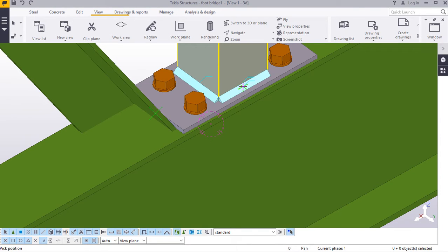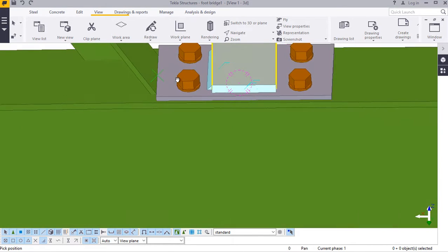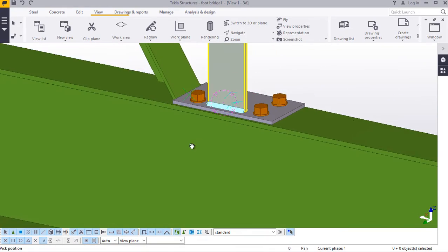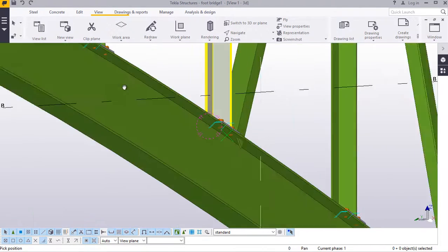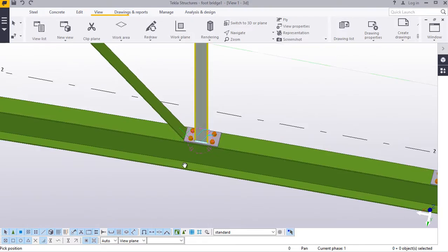I want to rotate the model about this spot. The moment you pick the point you want to rotate the model about, you see the cursor change to a hand. Click and press your left button on the mouse, and really you'll be able to turn this easily.